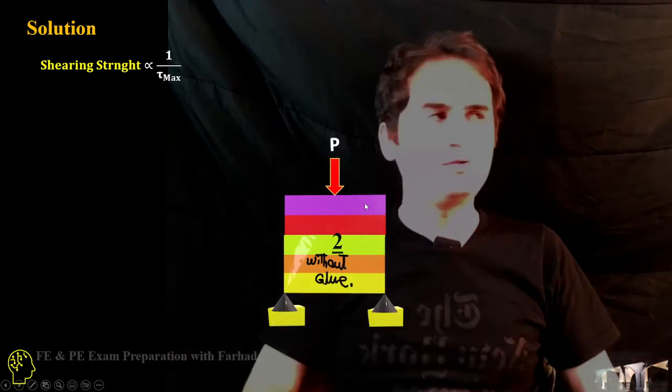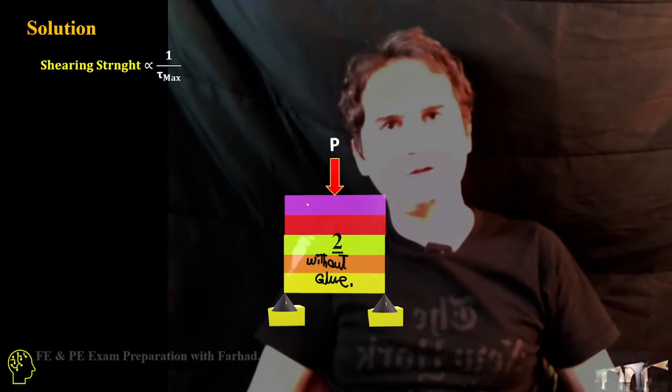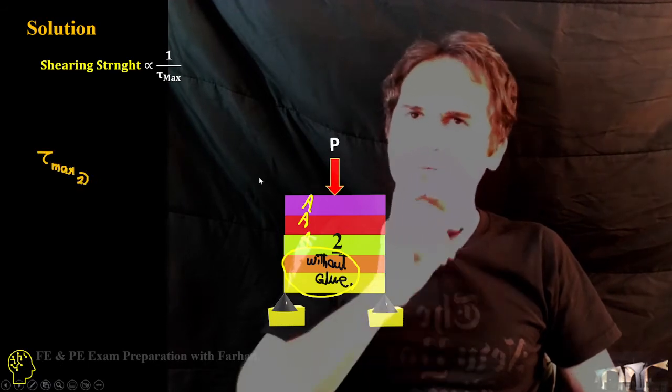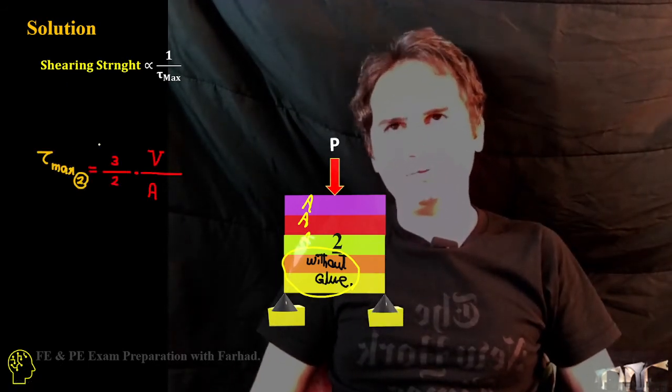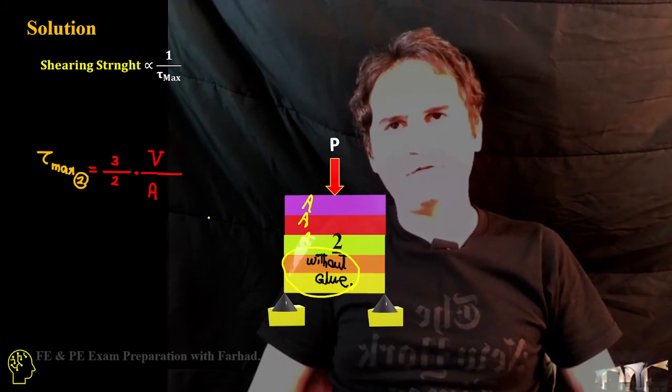And in scenario 2, when we just locate the boxes on top of each other, each of them has a cross-sectional area of A, and we don't use any glue in this condition. So tau maximum is equal to 1.5, again, vertical shear over the area.